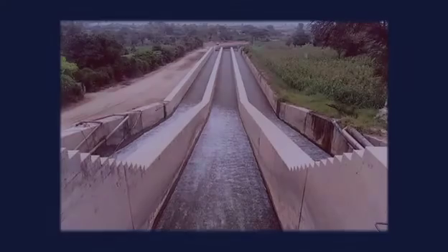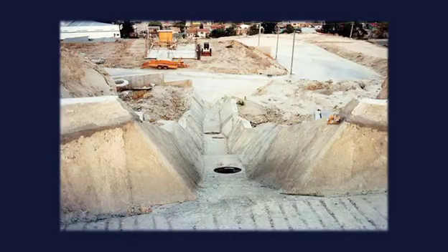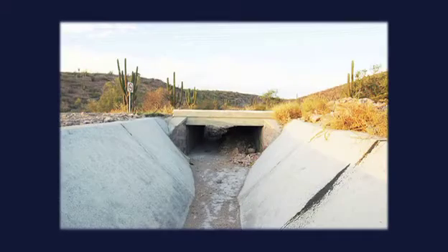The following are various names for engineering canals. 1. Canal, a long artificial channel, usually of mild slope, ground supported, either unlined or lined with masonry, concrete, or asphalt. 2. Flume, a usually short canal, supported above ground, made of wood, metal, or plastic. 3. Chute, a canal of steep slope, usually supercritical. 4. Drop, a very short chute. 5. Culvert, a covered channel of comparatively short length, which may flow partially full.